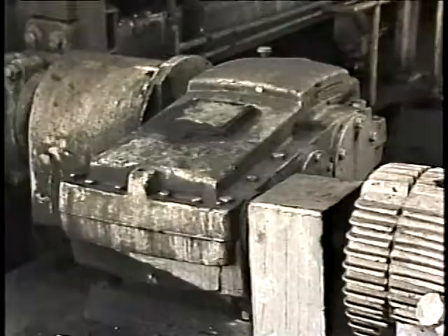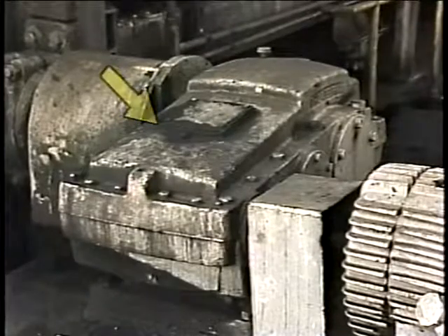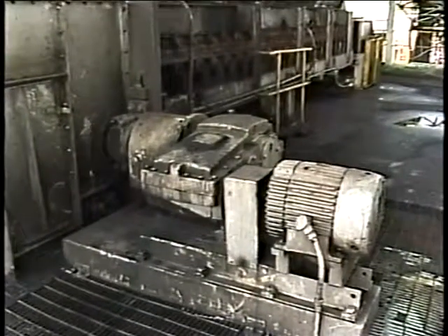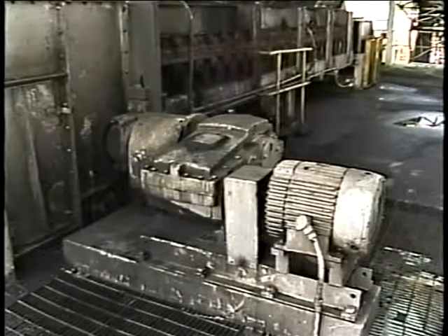So far in this program, we've looked at different types of gears and several gear sets. Many gear arrangements are enclosed in housings called gearboxes. Gearboxes also contain additional equipment that supports gear operation. So next, we're going to take a look at an actual gearbox and identify some of its components. This gearbox is used as a reduction gear drive for a conveyor. Basically, a reduction gear drive reduces the speed of the prime mover, such as a motor, to a slower speed required by the load, which in this case is a conveyor belt.